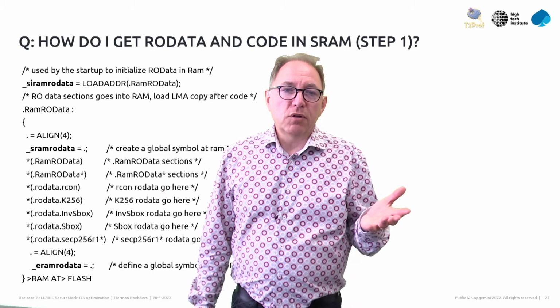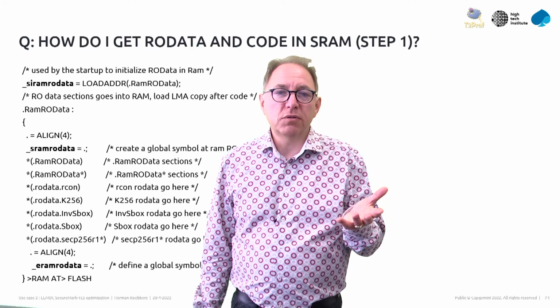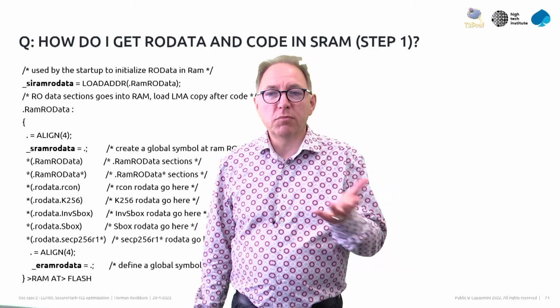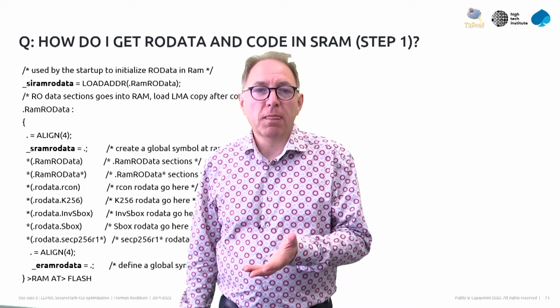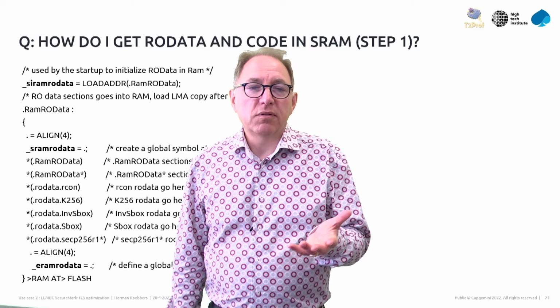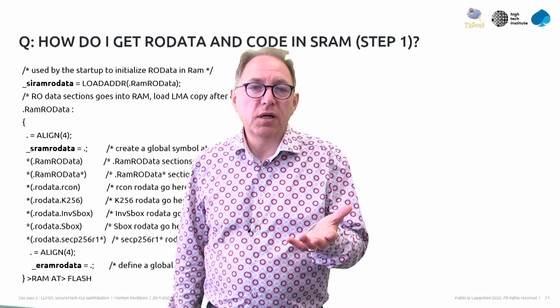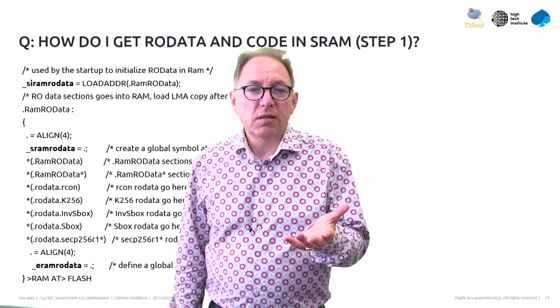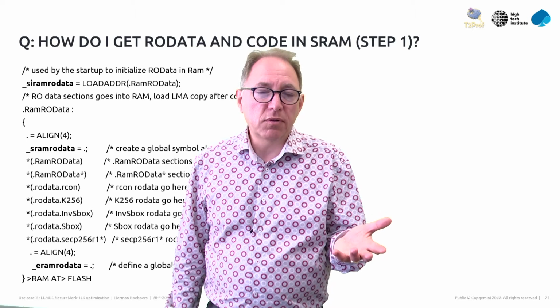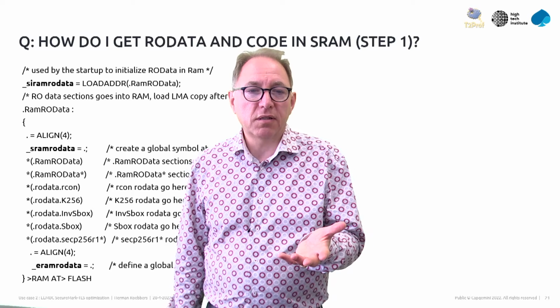Now, the fact that the code is there is not enough. We also need to make sure that it somehow gets copied into memory when the system starts up. So that is basically similar to what we did for code. We also do it for the read-only data, where we place this in RAM, not in SRAM2, but in RAM, because that is where the data lives.